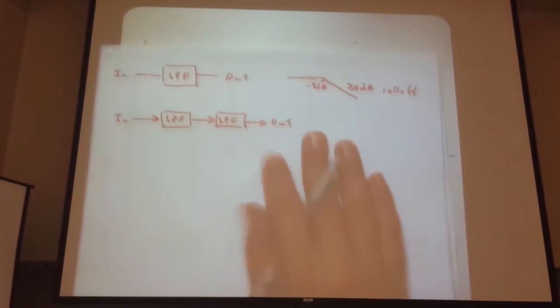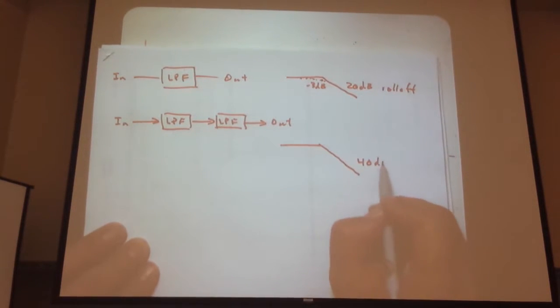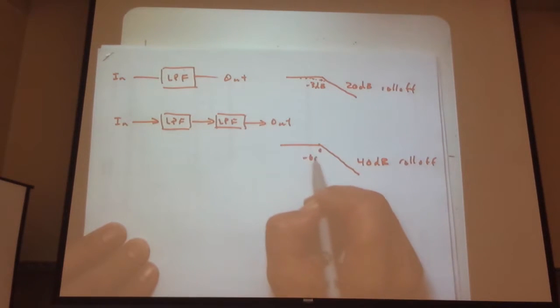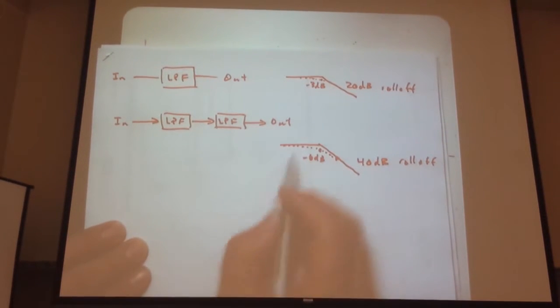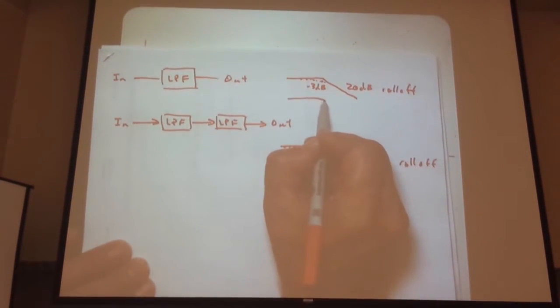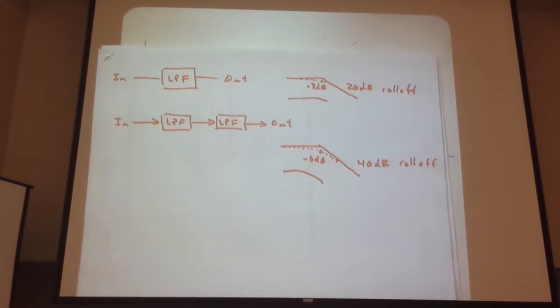And now where are we? Well, we have a steeper roll-off. Pretend that's steeper, 40 dB roll-off. But now we're down at minus 6 dB. And so our pass band, we kind of exaggerate things. Here's our pass band here, mostly flat with a little curve. Here's our pass band here, and we really kind of bend. All right, that's way exaggerated. But it's getting the message across. Our pass band attenuates more. And we can keep going, get higher, more steep roll off, but at a price.